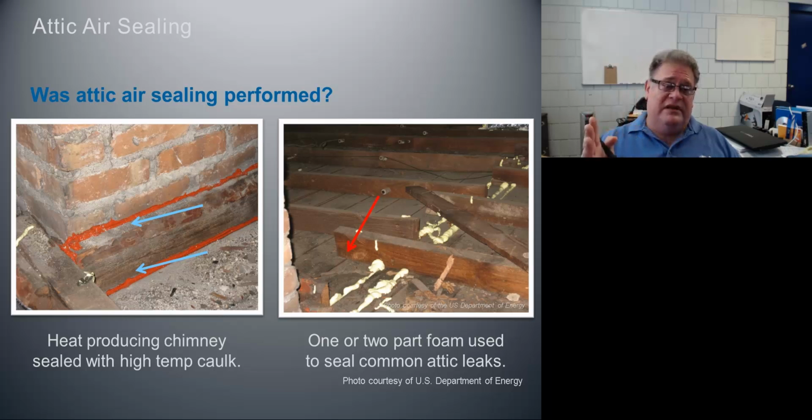Well, one of the first things you need to know is whether that chimney is still being used or not. If this chimney is still in use or has the potential to be put back into use, and is not one that has been taken out of service completely with just the bricks not yet removed, then what you're seeing here is probably acceptable. And you would say that work has been done, and note that the chimney is no longer in service and it's not serviceable. It won't be used again. However, if you think it can be, then this is probably deficient work. Work appears to have been done, but it's not to standards.